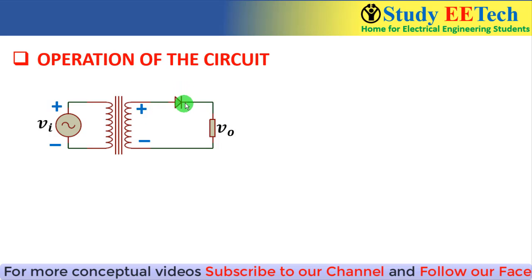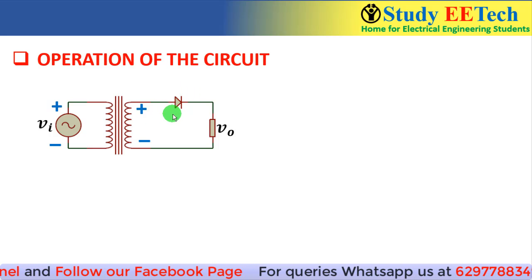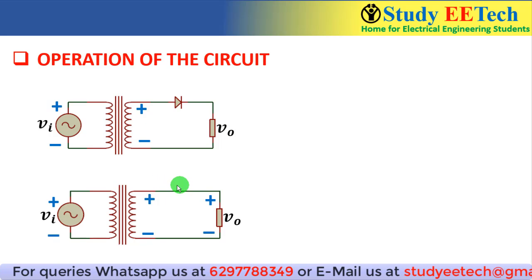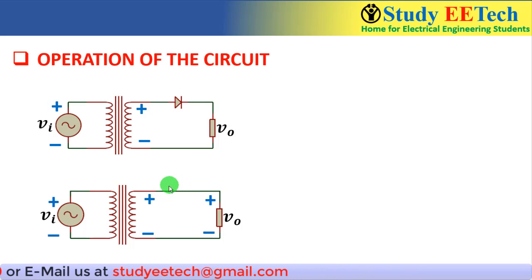That means the diode is in forward biased mode, and we have already seen that in forward biased mode the diode is a short circuit. So the equivalent circuit will be this one, where we have replaced the diode by a short circuit. We are assuming there is no voltage drop across the diode during its on state. So this positive voltage will directly appear here and this negative voltage will appear here, and we will get the output voltage. Now what will be the waveform?